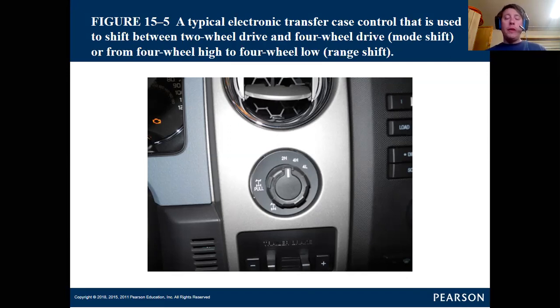We'll talk about how these manufacturers are splitting power. It's very odd, and it can be a little confusing. So let's start with this: how do we control the engagement of four-wheel drive? We can do it electronically, or we can do it mechanically. Electronically is what's right in front of you on your screen. We've got a selector switch. The selector switch is operated by the driver of the vehicle, and they give the computer an input of what they desire for their drive status.